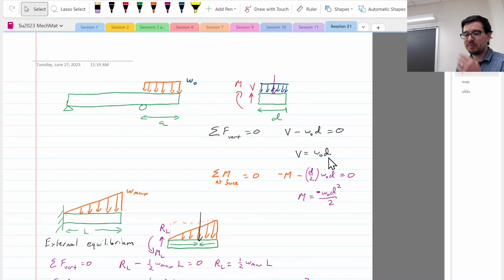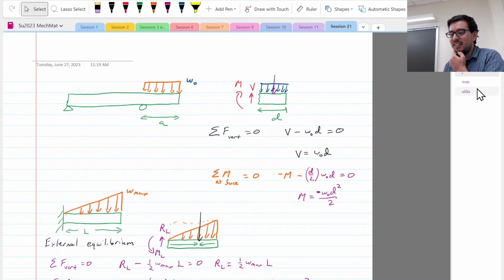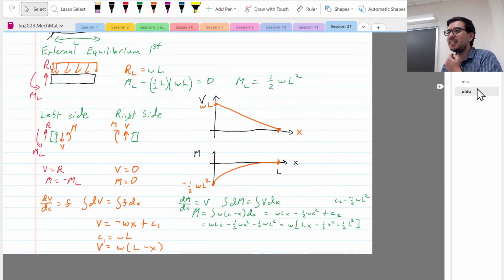Also, to do the bending moment diagram, can I just look at the area of the shear force and then do the changing moment and then just two points and look at what type of curve it is? That way I don't have to derive another equation for bending moment. Sure.